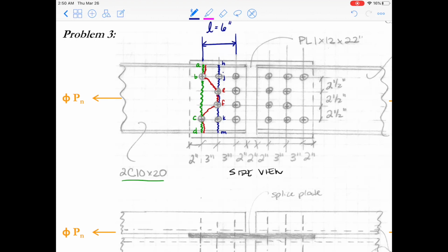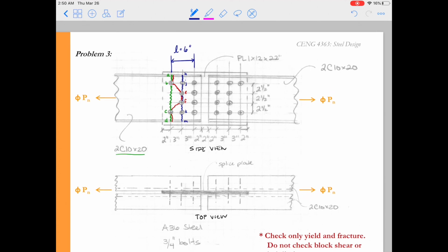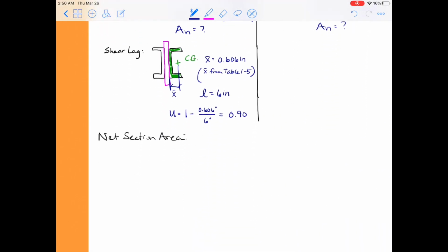HJEFKM, that line lies behind 2 of the 10 bolt holes, so it's subjected to a lower load. So we're going to have to multiply by that reciprocal fraction, 10/8, to compare it to the first 2 lines that we drew. So let's go ahead and figure out what our net section areas are. I'll set up my little table and I'll look at the different paths.